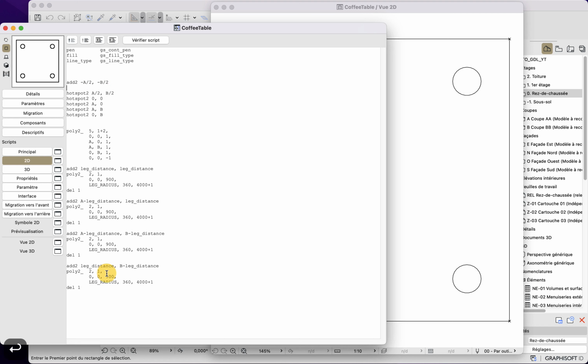And what we will do at the end is add a DEL statement. It is very important to have the same number of DELs as you have transformations. Whether they are translation, rotation, or stretching, you need to be neutral when it comes to the transformation stack. So it's almost mandatory so you can have a proper object.